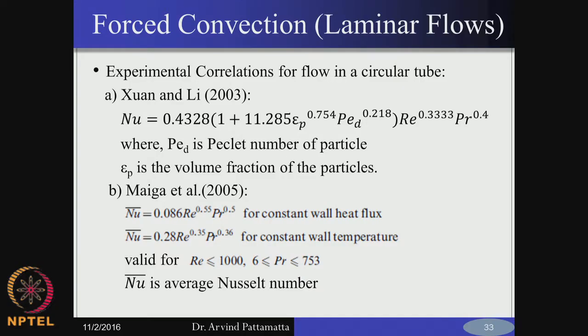The thermal conductivity enhancement will already contribute to conduction heat transfer, but we are only looking at the temperature gradient, which is the measure of convective heat transfer increase. So, clearly most of the experimental studies agree that there is an increase in the Nusselt number with the addition of nanoparticles, but only the percentage increase is not very consistent. Some people claim it can be 10%, some 15%, or some 20-25%. So, there is not a very consistent number.